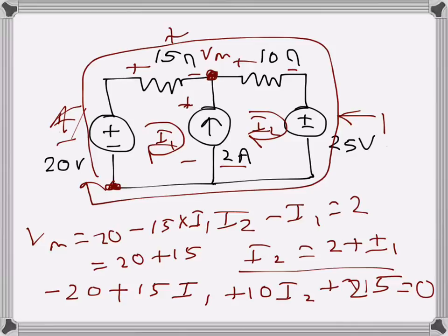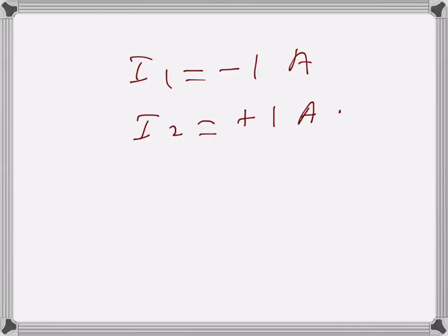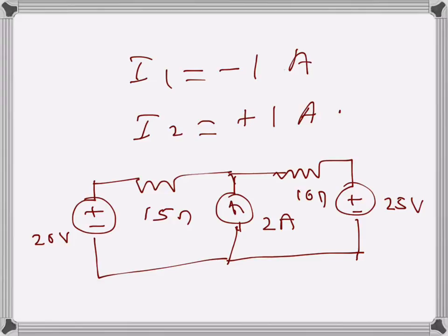So if we see the other way, if we do the node voltage method, I have drawn the circuit again. I am doing the node voltage method now. So this is my reference voltage and this is the voltage, let's call it Vm. So there is basically only one unknown, just one equation. So I just write KCL at this node. So that will be the outgoing currents, and this current which is incoming. So we will have three currents.